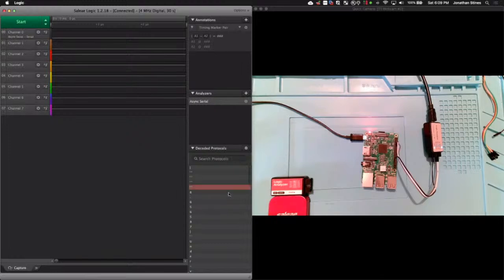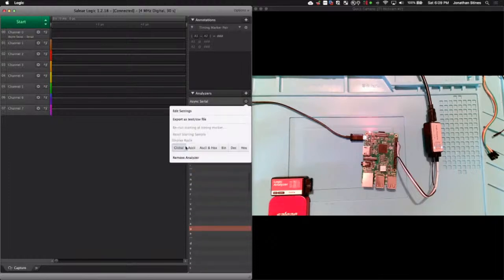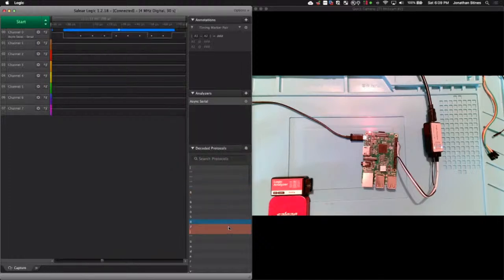And taking a peek here real quick, we can see in the decoded protocol section that we actually have the output of what we saw over the UART interface. Under voltage, it's printed kind of funky here, but that's the actual output of what it's seeing. We had it set to ASCII, so the output is being displayed in ASCII format. Kind of neat. You can see all that kind of stuff. Scrolling even further down, we have detected and so on. But go to the very bottom. Maybe we missed it, but it would even capture, yep, there we go, the Raspberry Pi login.